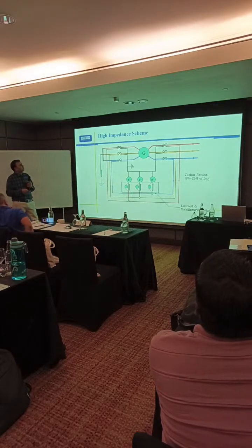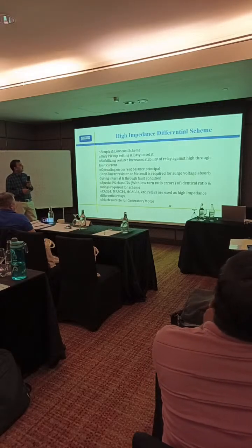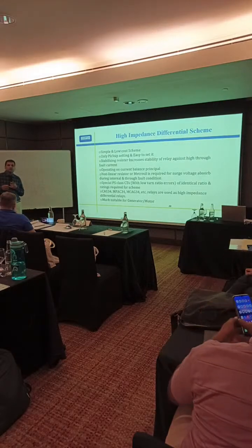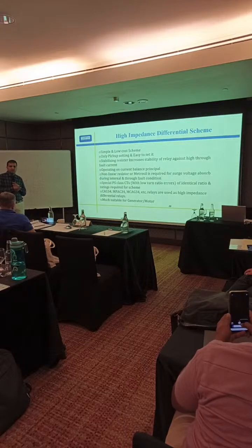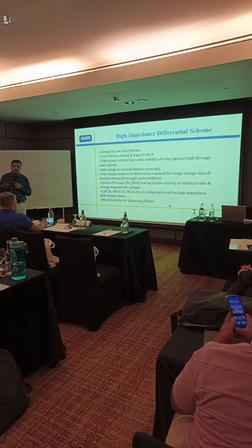In the high impedance scheme, all the CT ratios should be the same. In this, only the pickup setting is there. Earlier we mostly used this protection when numerical relays were not available.